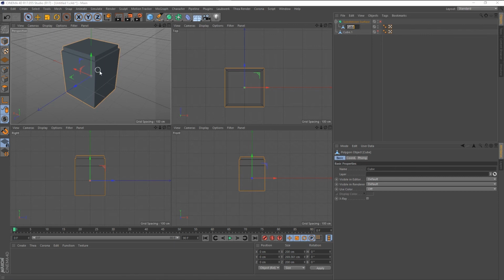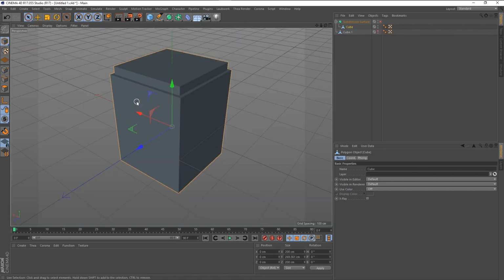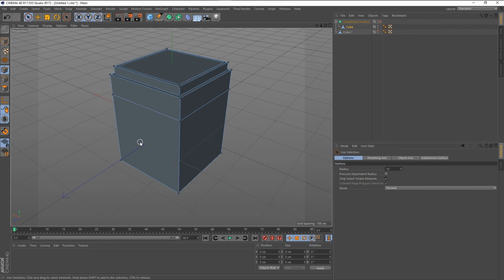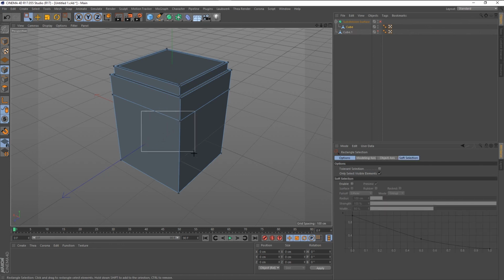You can hit enter to jump in. I'm going to expand this view out by center clicking on my mouse, and then I hit enter to go back into it. And then I hit 9 and I middle mouse click. I can expand my circle select for live select, 9 for live select, 0 for window select. I can hit enter again, and now I'm in selection of edge mode.